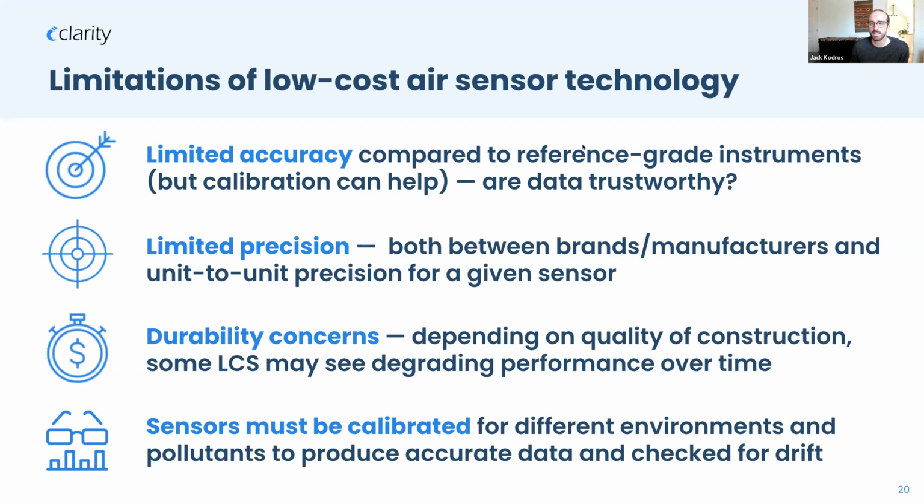So one of the big things that we think about a lot, and what I really want to impart to everyone in this presentation, is that, again, there's no free lunch. We can't have a cheaper air quality sensor and have it be as accurate and reliable as an instrument that costs tens of thousands of dollars. We have to give something up and we get something back in return. So I want to go over the limitations of low-cost air quality sensors and what we can do to work with those limitations.